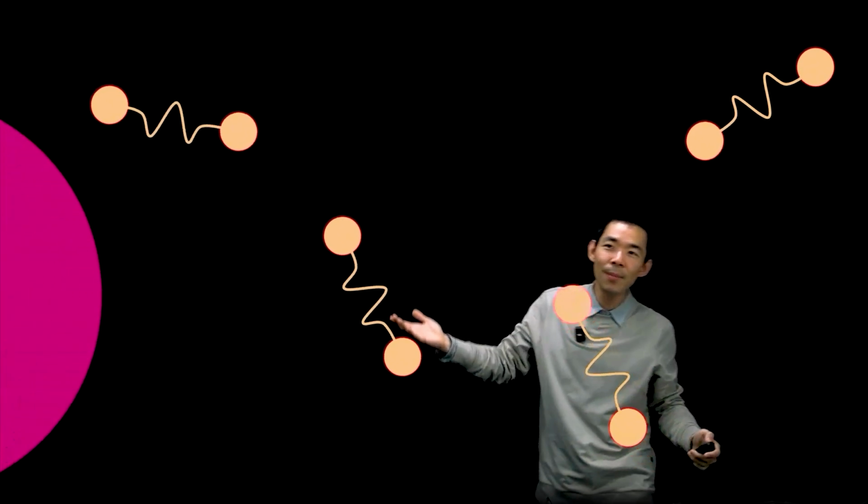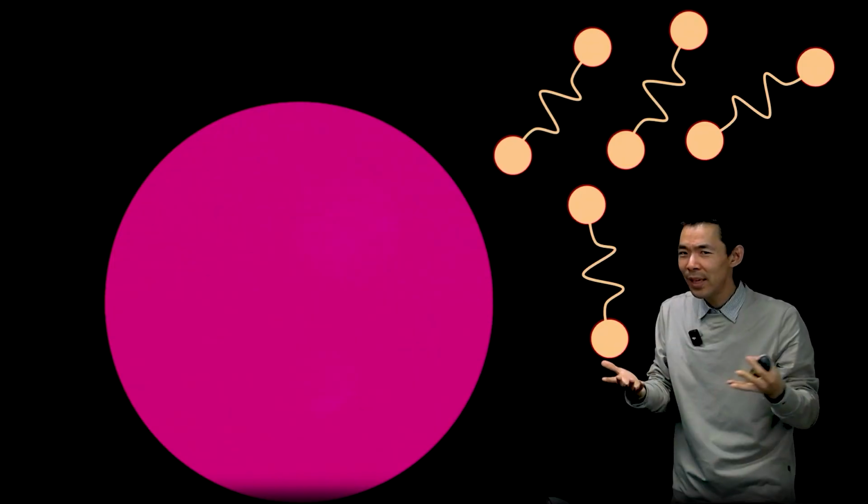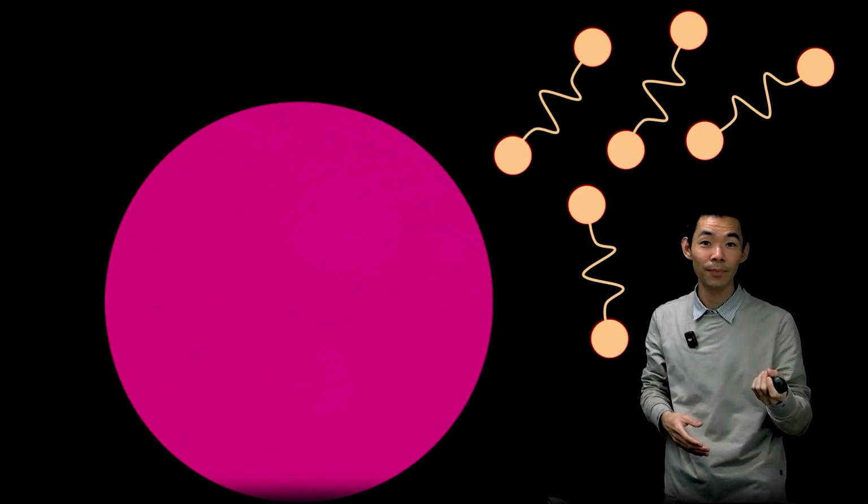But if you have some kind of forcing that causes heterogeneity of the entanglement sites or the polymers themselves, then the assumption of the homogeneous polymer is not a good one. And you can't use the standard constitutive equations that everyone's using. You would need to couple the density field of the beads to the stress tensor and the conformation tensor to come up with a more appropriate non-homogeneous constitutive equation.